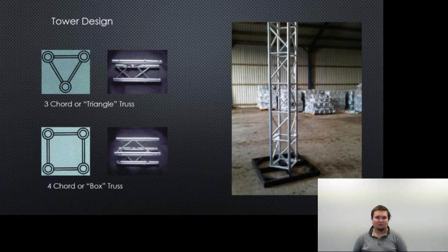Another advantage of the box truss is its simple design, which makes it easier to analyse. Having said this, we do realise that the box truss is heavier and more costly, but we have evaluated these downsides and have come to the conclusion that the benefits outweigh the disadvantages. In order to combat having chosen the heavier and less manoeuvrable box truss design, we have decided to incorporate a mechanism for separating the tower into 2 halves, making it much easier to transport.